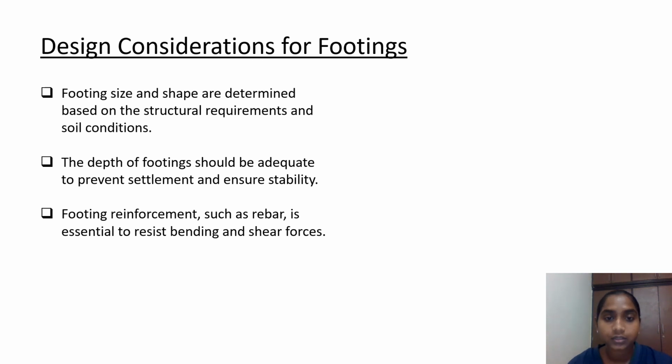Design considerations for footings. Footing size and shape are determined based on the structural requirements and soil conditions. The depth of footing should be adequate to prevent settlement and ensure stability. Footing reinforcement such as rebar is essential to resist bending and shear forces.